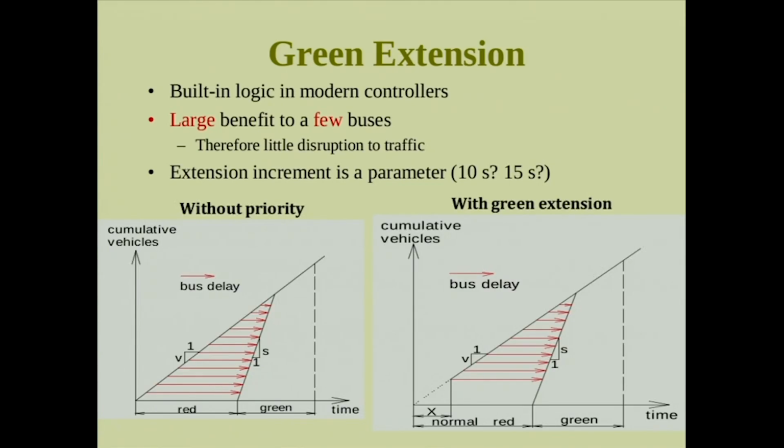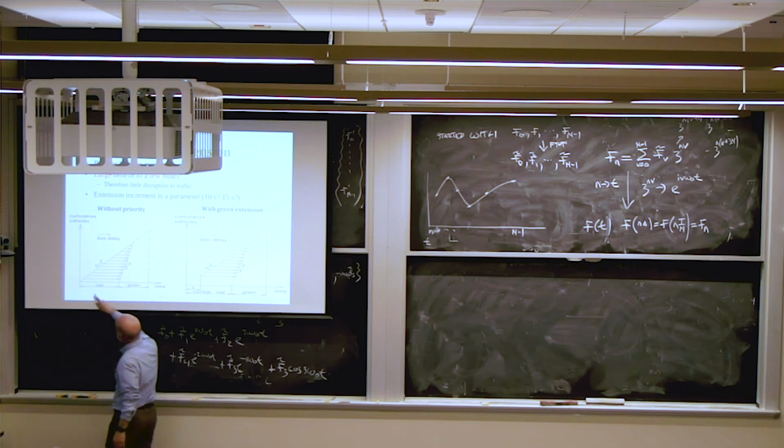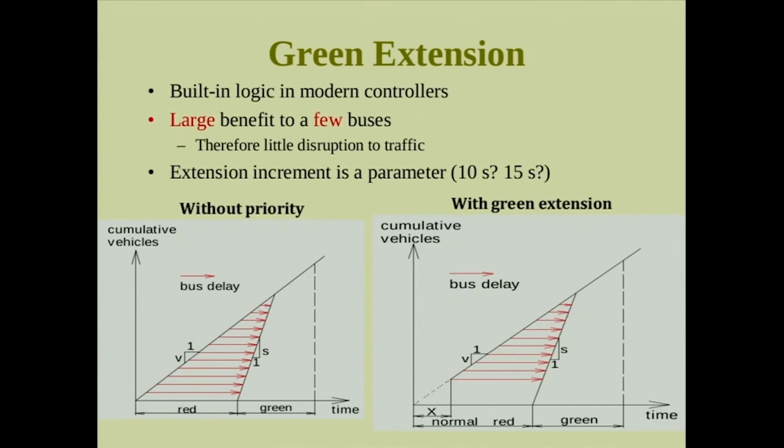Yeah. So the red lines here represent the time that a person is in the queue. So like the car arrival, here's arrival number 1. And then this line is the departure curve. Cars arrive at a relatively slow rate, let's say 1 car every 5 seconds, and they pull out at a much faster rate, say 1 car every 2 seconds.